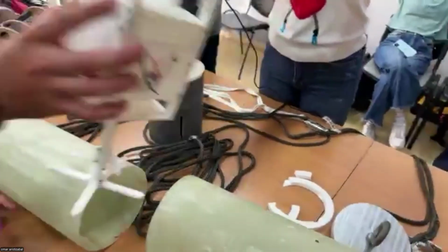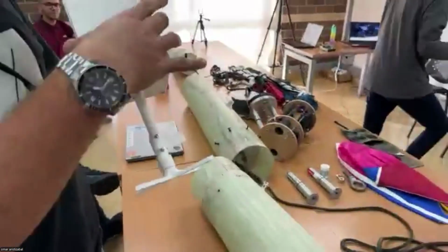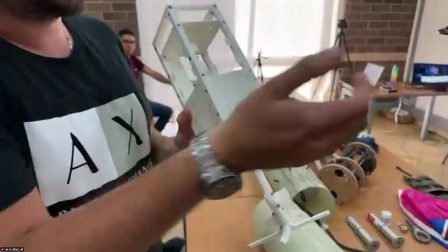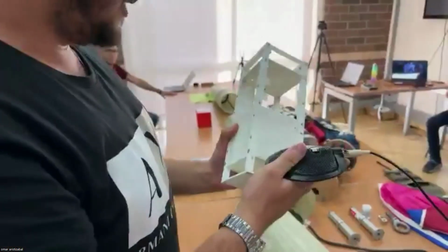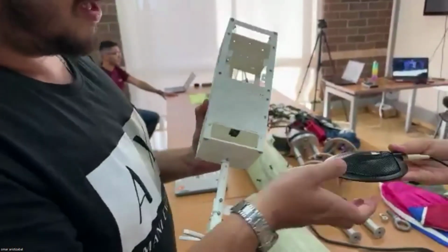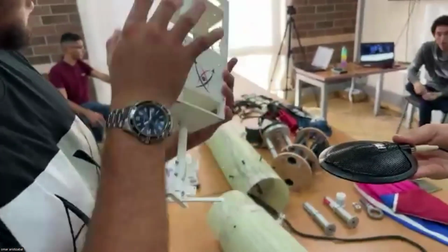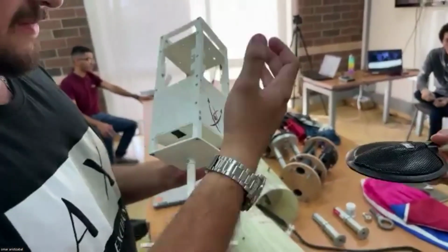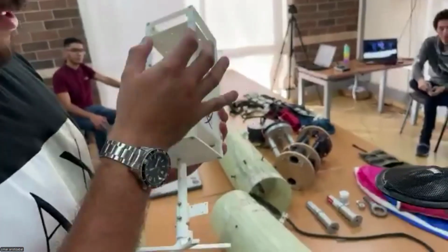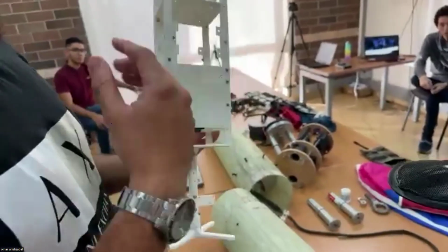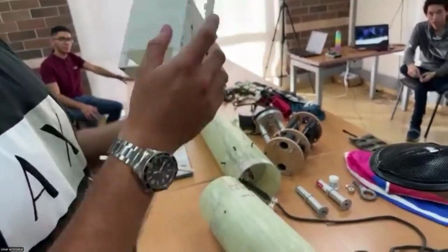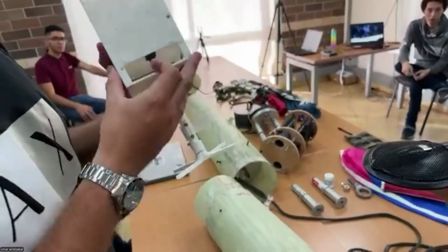What you see here, these boxes, is a product cage that we put in the CubeSat because the electromagnetic fields of the batteries, the bulbs, and also the pump were going to affect the measurements and the functioning of the PCB.